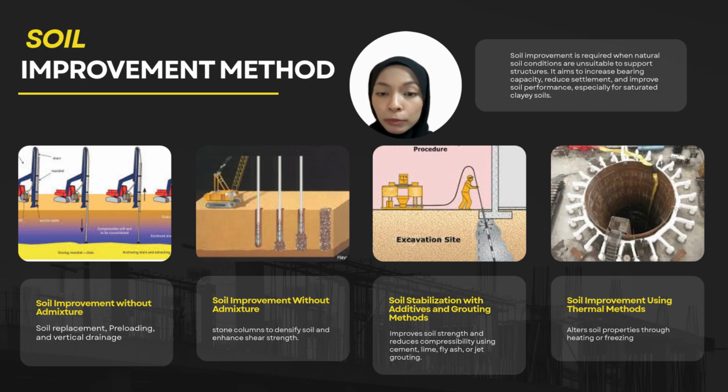Second, soil improvement with admixtures or inclusions such as stone columns, which densify the natural soil and provide additional support. Third, stabilization using additives and grouting methods including chemicals, cement, lime, and fly ash stabilization as well as jet grouting to strengthen soil and reduce compressibility. Lastly, thermal methods like soil heating and freezing can significantly alter soil properties, though these are the most costly. Overall, the choice of method depends on the soil type, project requirements, and desired performance.